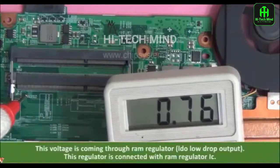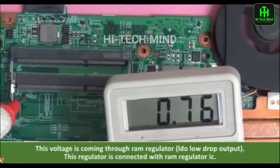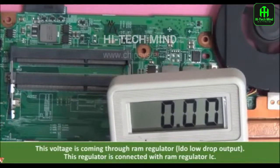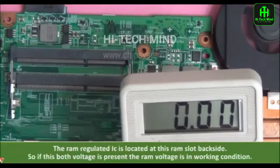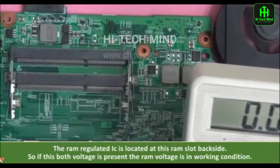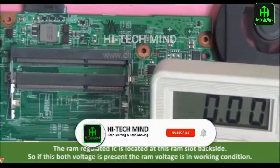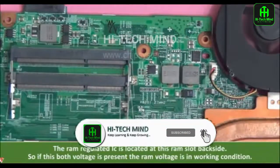This voltage is coming through the RAM regulator LDO, that is low drop out. This regulator is connected with the RAM regulator IC. The RAM regulator IC is located at the back side of this RAM slot. So if both these voltages are present, the RAM voltage is in working condition.